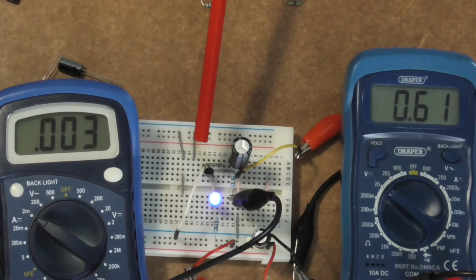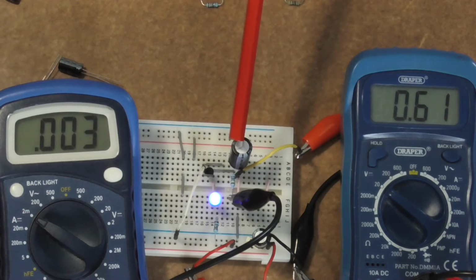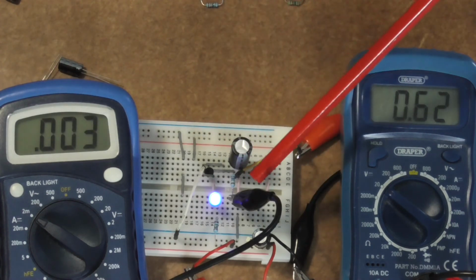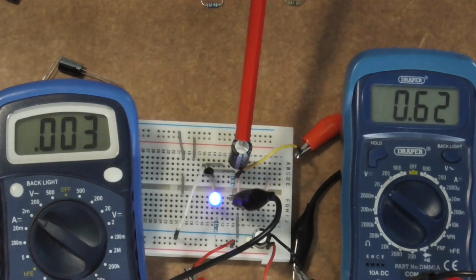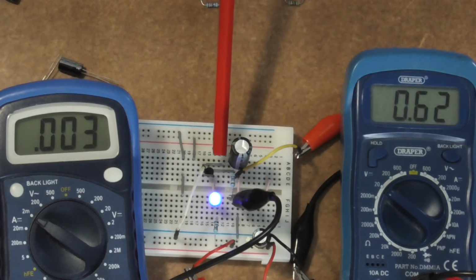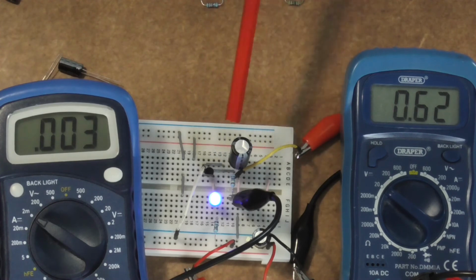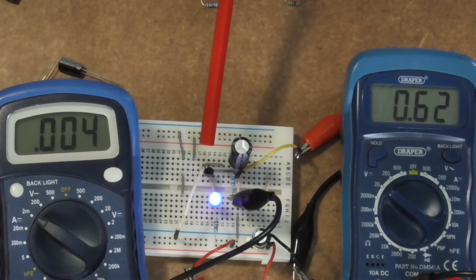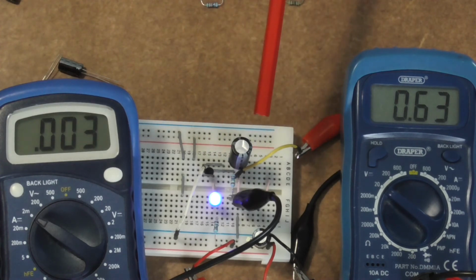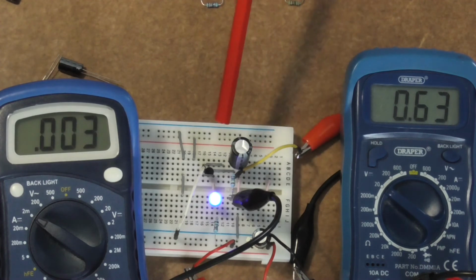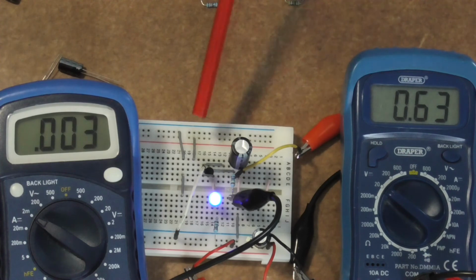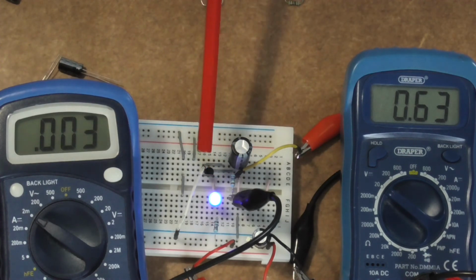But of course, because of the way that this resistor is allowing this capacitor to charge up, as that junction turns on we'll reach a point where it can't charge up anymore because it's discharging as quickly as it's charging to hold the voltage, which is just about enough to make the junction turn on and make the transistor work.